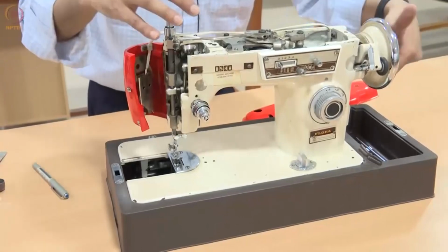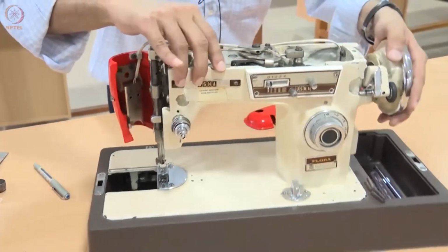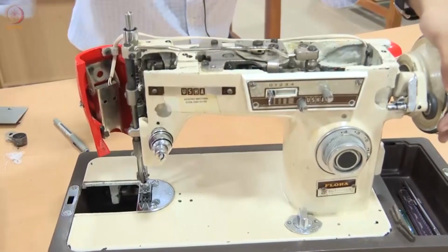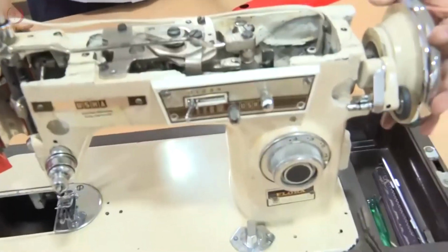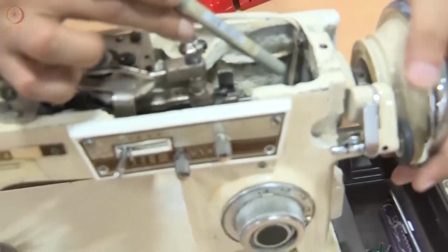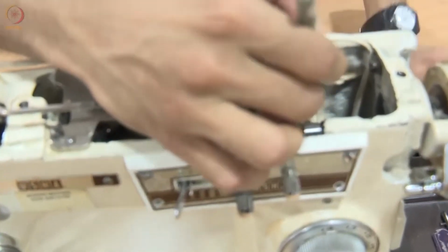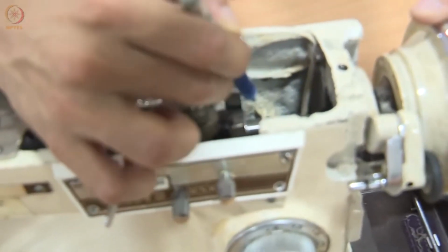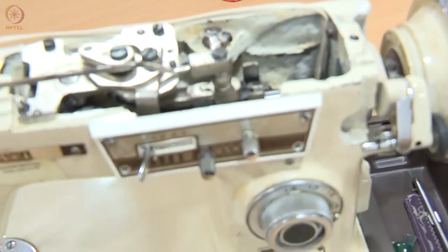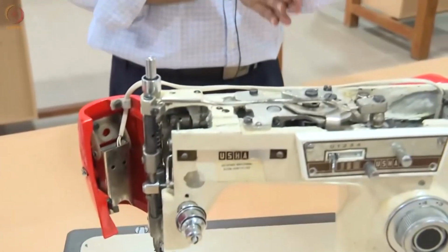So now let us go one by one. We have what is called a crankshaft. You can see this is a common shaft and this is called a crankshaft. If you look at any internal combustion engine, it has a four-bar mechanism. It has what is called a crank slider, right? In this case, it is flipped. In an internal combustion engine, we have a piston that drives the crank. In this machine, we have the crank that drives the sliding member. In other words, we have a crank slider mechanism.